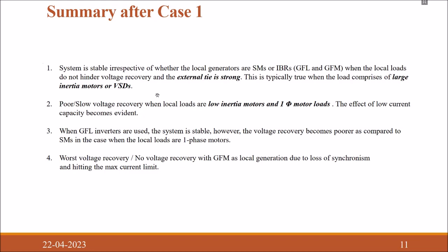Second, when GFL inverters are used, the system will be stable as long as we have a PLL which is working perfectly, and the voltage recovery will become poorer for single phase motors. We see that the grid forming inverter is not able to work properly, or becomes unstable, because of hitting its maximum value. And for single phase motors, even the voltage recovery of GFL is poorer as compared to synchronous machines.